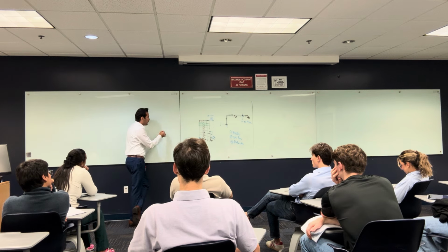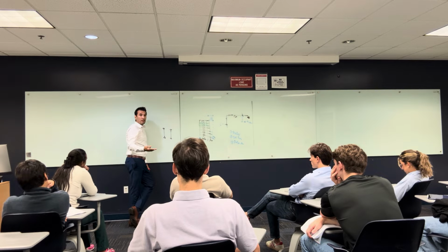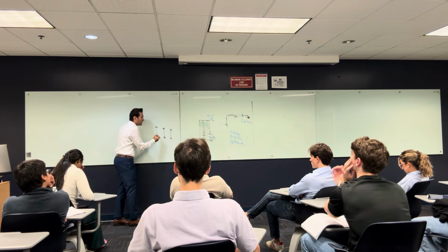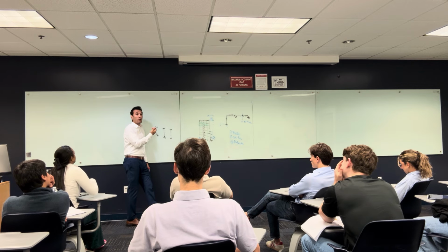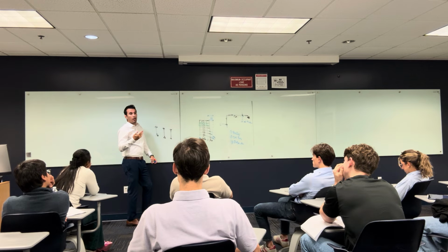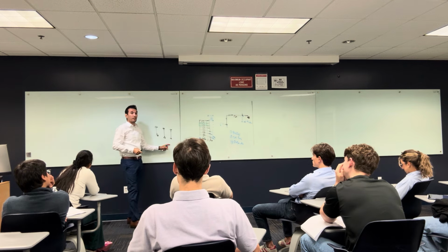Let's say if your element is hinged versus fixed and you apply load, it will have different stiffness, because when you fix here, you are increasing the stiffness. But if you have this hinge, the stiffness is less. When you have something like this ruler, you are decreasing the stiffness. So it depends on the geometry, the boundary conditions, Young's modulus, cross-sectional area, and the moment of inertia. All this affects the stiffness of the element.